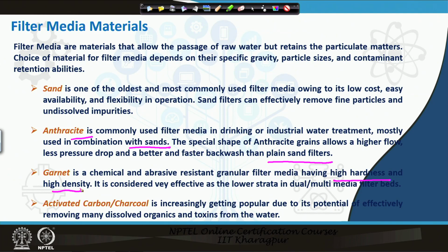The other added advantage is that it is resistant to any chemical reaction or physical abrasion. That is why it is considered very effective as the lower strata in dual or multimedia filter beds.